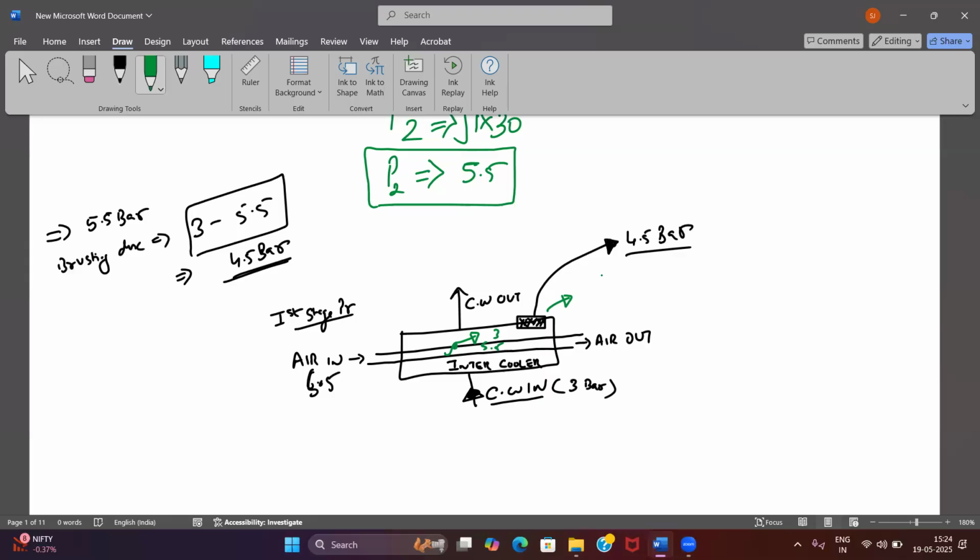Sir, it will be more than the discharge pressure, right, the bursting disk? Okay, more than the first stage discharge pressure. Suppose it is bursting at 6 bar. What is the condition? Suppose our first stage intercooler leaks. Will this bursting disk burst? No, sir. It will never go above 6 bar. No chance. If the maximum pressure is 5.5 bar, how will it go to 6 bar, right?